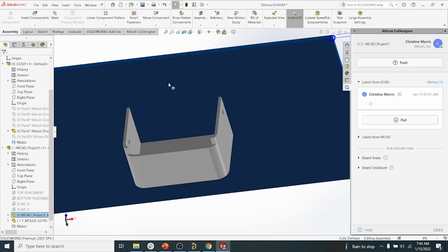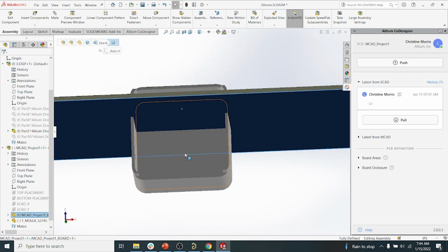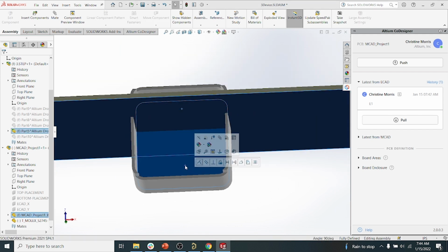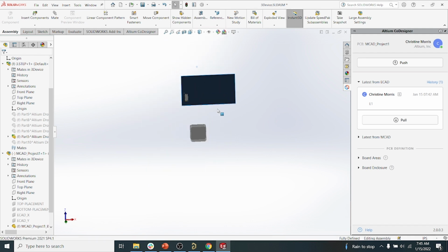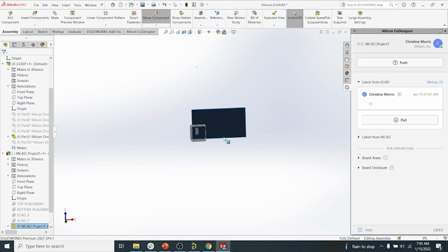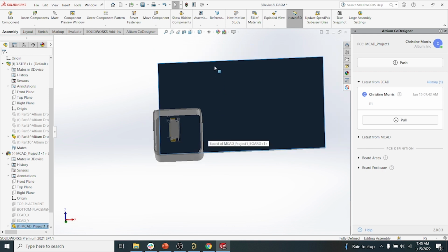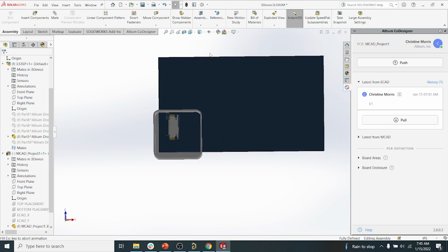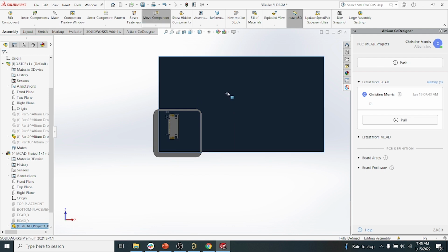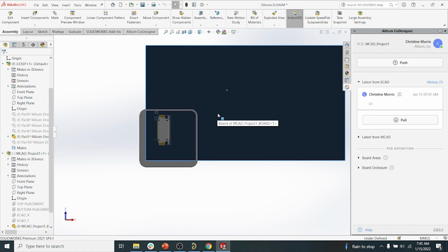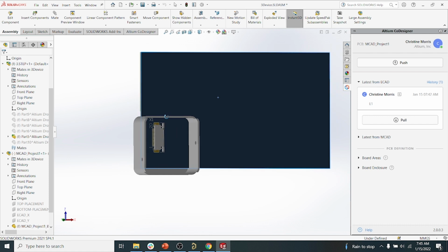And I'm just going to make a coincident mate so it'll be oriented the right place or direction as well. I'll just bring that in closer, and we can go ahead. And at this point, now I have my board, and I want to be able to constrain it a little bit more. I'm just going to change my units here real quick. And then I'm going to add a couple of mates.